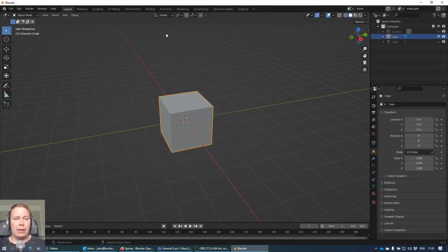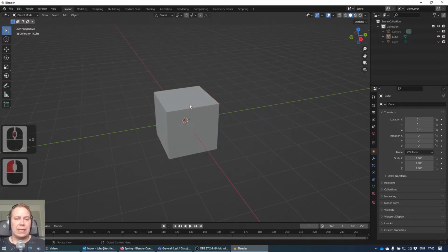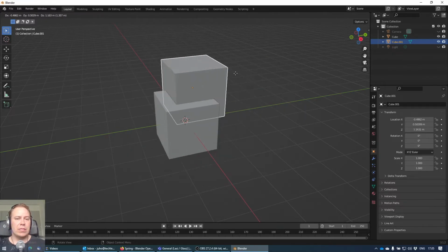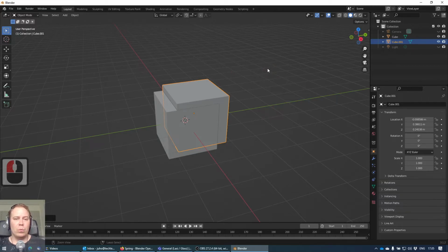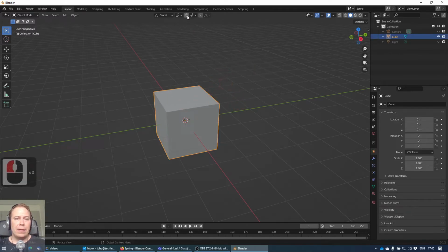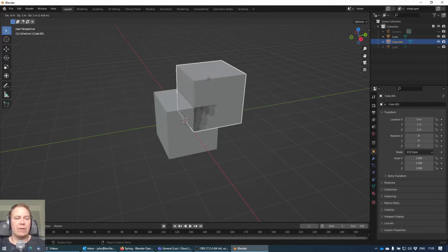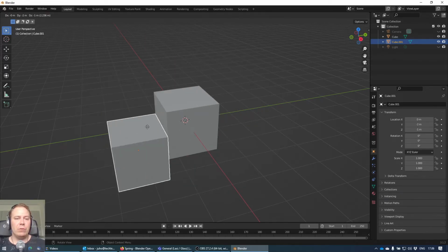So here on upper corner you have this magnet that is called snap. When you are basically having many cubes like this, let's create one more. It's really hard to place these objects around the scene. It becomes weird. By the way, you can erase this one by clicking on X and then delete. Okay, so select this snap option, and then when you click on Shift D, that duplicates the thing. You can see that it's kind of snapping around the 3D view.